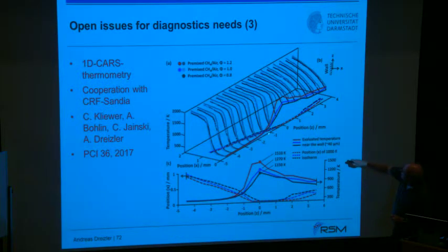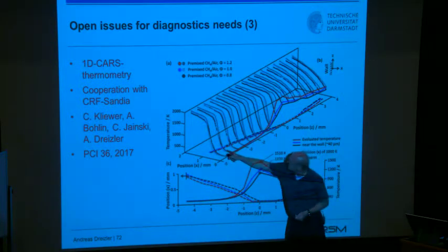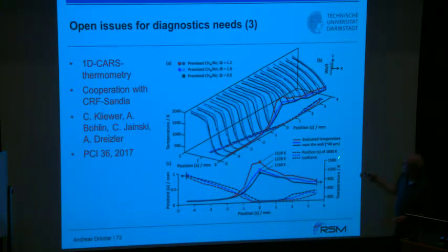How 40 microns from the wall, here the temperature goes up and reaches really high values, and that would be the approaching, here would be the quenching, and here would be then the diffusion, the transport part, the post-quenching. And you see here as well these dashed lines. Those are the positions using a 1000 Kelvin isocontour where it comes closer and closer to the wall, to the quenching, and then bounces off because of diffusion.